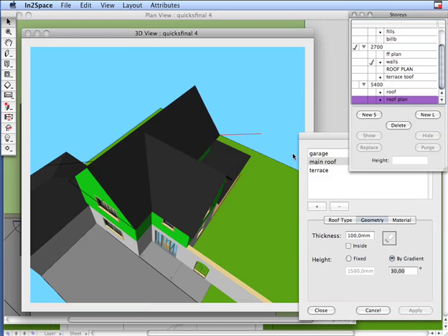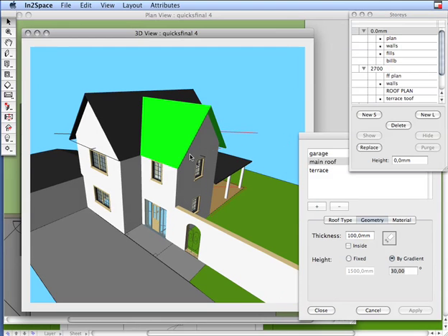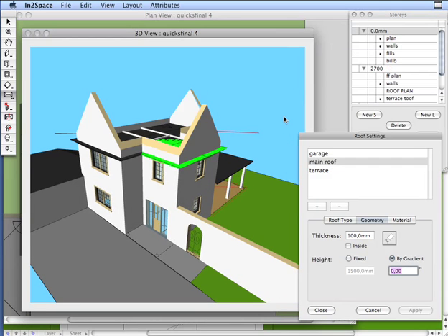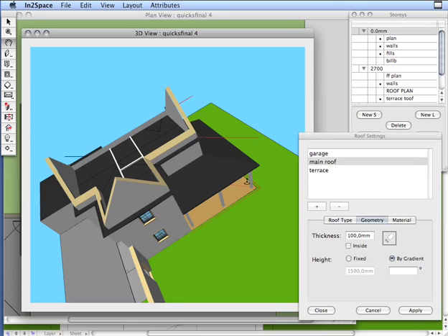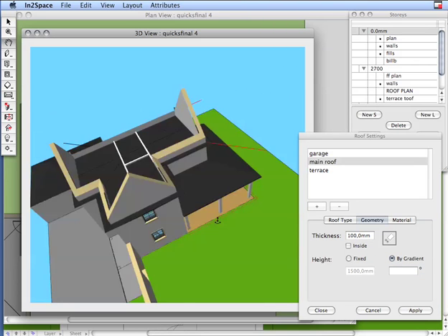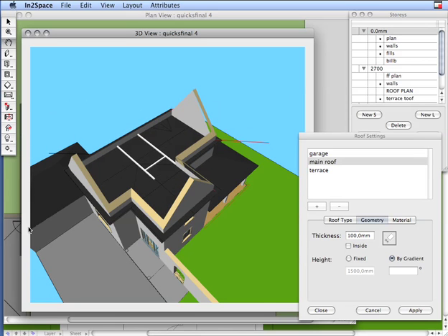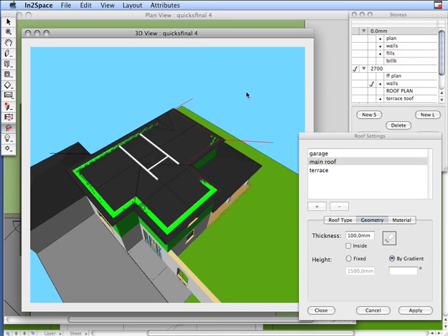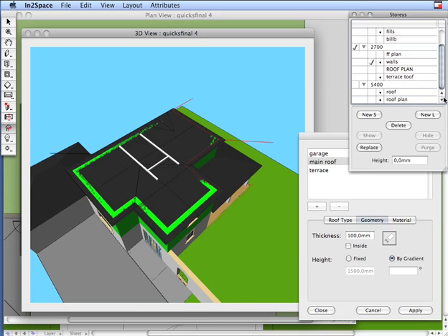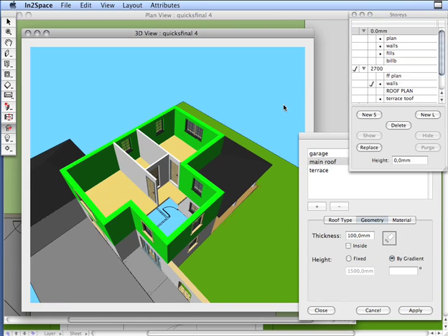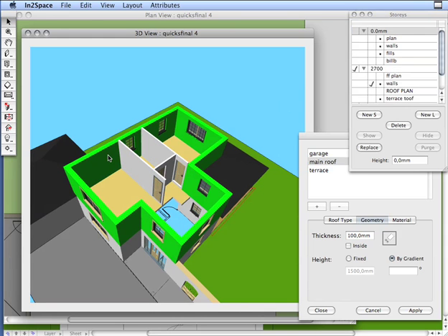Well, if we bring our roof back, the process will work in reverse. So if we create our roof at 0, 0, like so, get a good angle from which we can work, use the extend to roof tool, and it will work backwards. Turn our roof off, and we've got a flattened out expanse again.